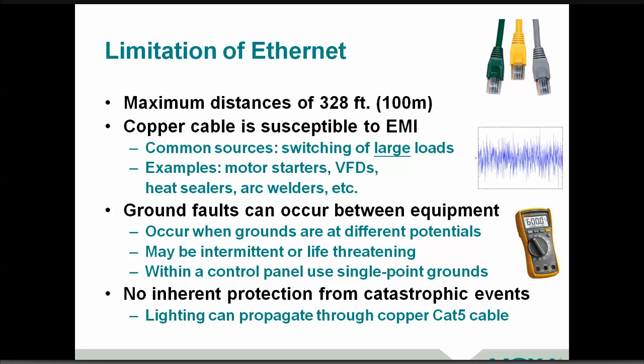That might be things such as other electrical devices nearby. And within industrial applications, we see a lot of things that are switching large loads, turning a motor starter on and off for a pump or a compressor. If you're doing variable speed applications, you might have a variable speed drive or a variable frequency drive, a VFD. You could have other types of equipment. Maybe within a manufacturing facility, you might be doing maintenance on a system and maybe having to use an arc welder nearby.